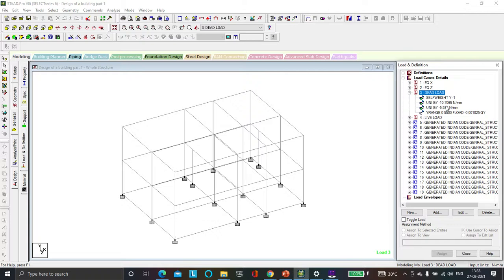But in the other case of dynamic analysis, there is a time dependency. So what matters is the intensity of the load and the temporal distribution of the building. So in dynamic analysis, time is a variable that we need to consider. In dynamic analysis, there's one analysis that we use, called mode analysis. So mode analysis is a simple way to calculate the natural frequencies of your system, so you know which frequencies can be destructive and dangerous for it.